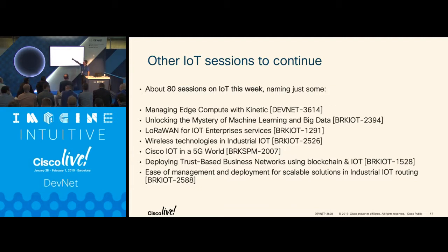The advantage of LoRa is that it has a very, very long range, multiple kilometers. It's very, very low power. With a single cell lithium battery, you can last for 10 years if you send just a couple of messages a day. So there is a number of very interesting use cases for smart cities and things like that.